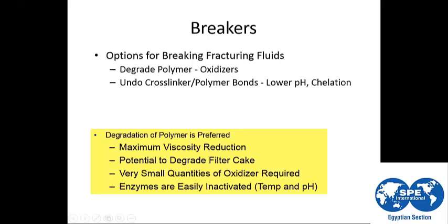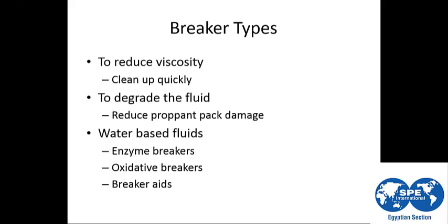It is guaranteed to maximize the viscosity reduction of the fracture fluid, so it is easier to recover and reduces the potential of damage by the frac fluid. Okay, we have the breakers used to reduce the viscosity for quick cleanup, to degrade the fluid and reduce proppant pack damage. Okay, for water-based frac fluid, as we said, we use oxidizers, or we can use enzymes,